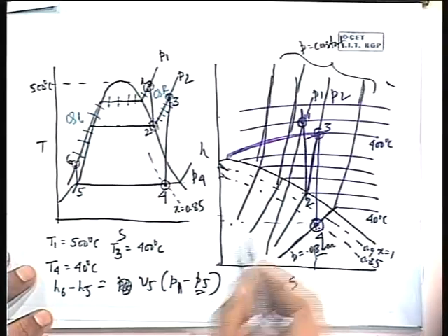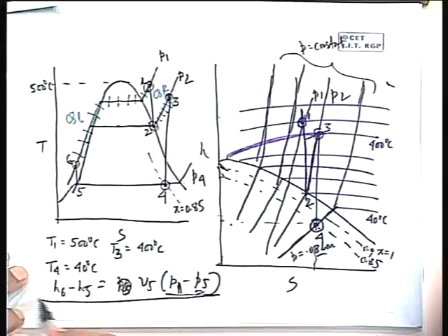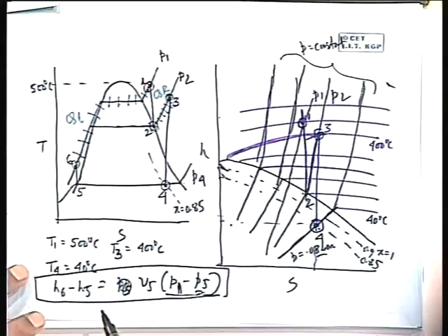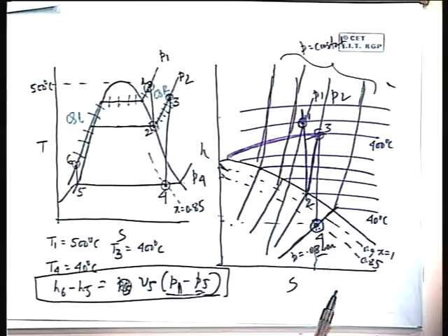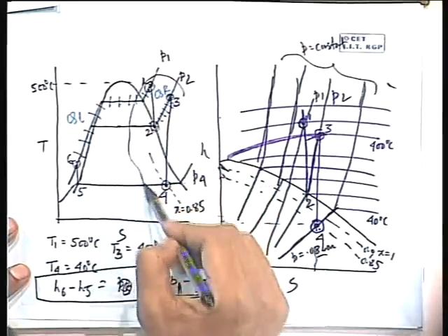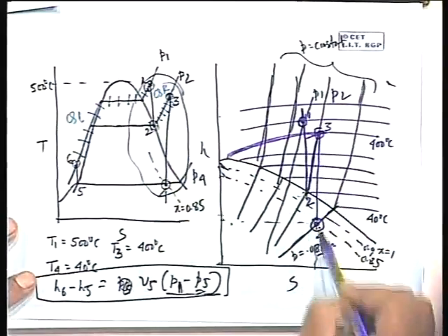that means P1. So that means this has been found out by the application of steady flow energy equations and considering the process to be isentropic and the water is incompressible, so that specific volume between 6 and 5 remains almost the same. This has been discussed earlier, so you get everything. That means this part of the cycle diagram is generated here.